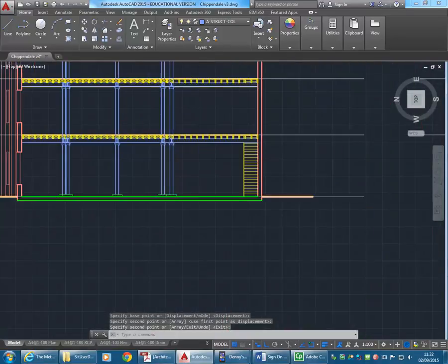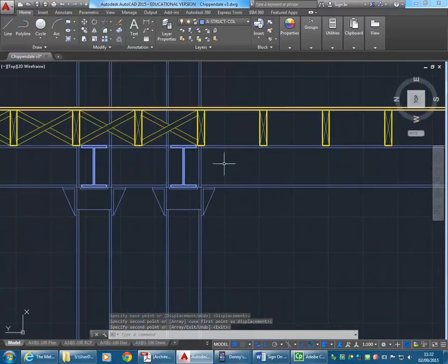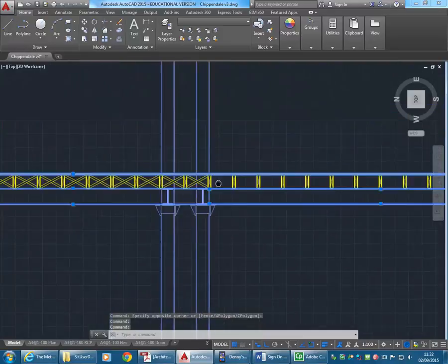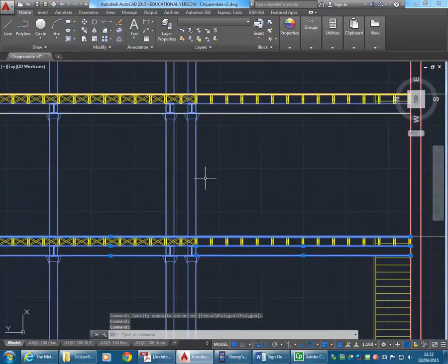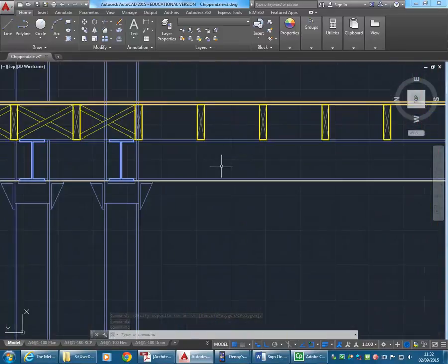And then the lines from the beams and the joists would be very similar as well. So a lot of those can just be copied across. Remember, you're not going to see the joists cut, so you just need the top and the bottom to show. The floor as well, so that can be copied across. And you can do all of those levels together.